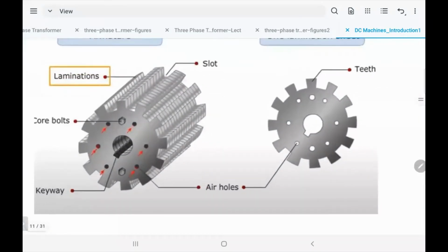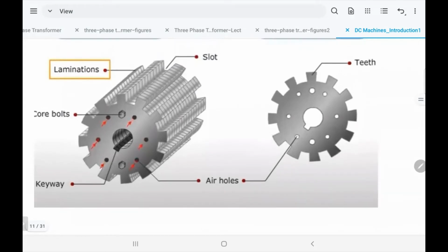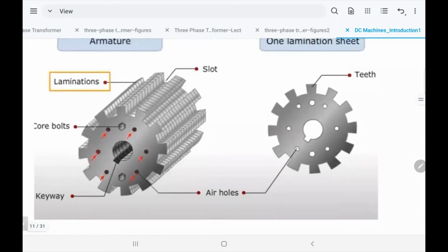That's the way they do the rotor, by the way. They have the teeth, and then they put like 1,000 of them, but they are all insulated. Between this sheet and the second one, there's insulated material between them, not touching. Why? Also for the eddy current. They have big current, they have many coils. And of course, there are the air holes here for ventilation.